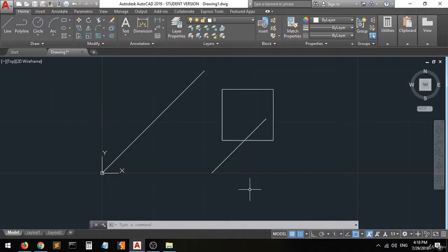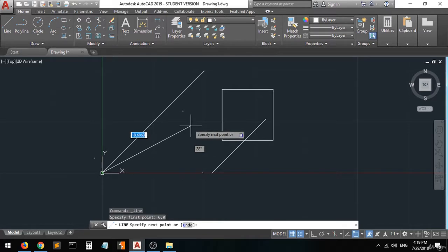Now as you can see, using the at sign will do it relative to the start point, okay? But when you don't use the at sign, it will be calculated from the origin. Be careful. So, if you do this, select the line and then specify the first point, not picking any point from here. Let's do 0/0, enter. You can see that we have started from the origin point. And then now don't type the at sign.